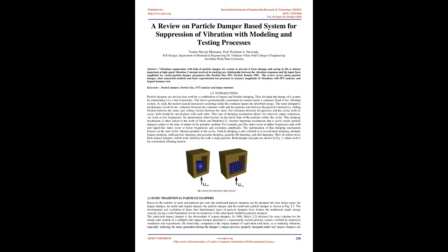Concepts involved in the study are the relationship between the vibration responses and the input force amplitude for varied particle damper parameters like particle size, PS, and particle density, PD. The review covers particle dampers, their numerical methods and basic experimental test processes to measure the magnitude of vibrations with FFT analyzer and impact hammer test. Keywords: particle damper, particle size, FFT analyzer, and impact hammer.